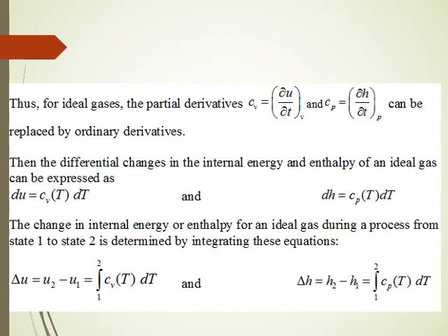The third method could be by using average specific heats. This is very simple and very convenient too when property tables are not available. The results obtained are reasonably accurate if the temperature interval is not very large. So normally, while doing calculations for engineering thermodynamics at the elementary level of the BTech program, we definitely go for the third method, that is, we use average specific heats as they are provided in the books, or they are provided in the question paper in the examination.